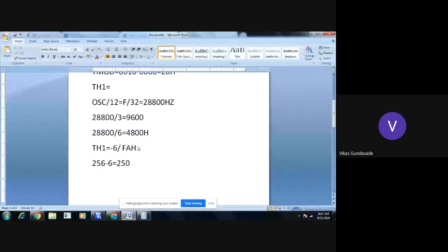into TH1. Okay, and after that, to set the SCON register, the upper 2 bits of the SCON register are mode 0 and mode 1, which is for mode selection. By default we need to take mode 1, because it is variable baud rate. So for mode 1, SM2 bit will be 0, receive enable you can keep as 0 or 1.